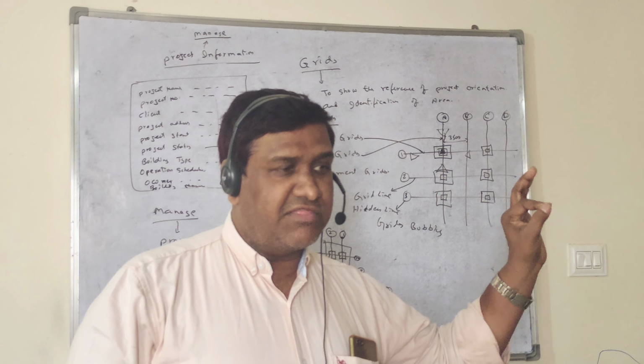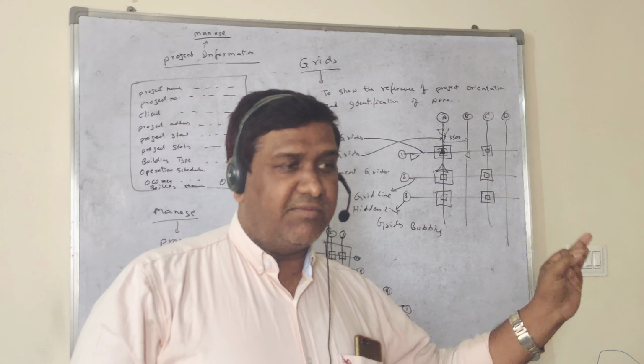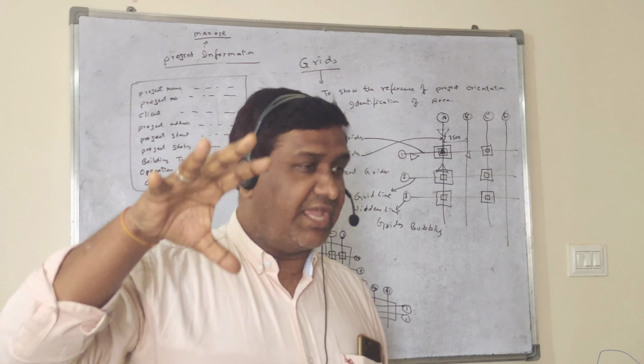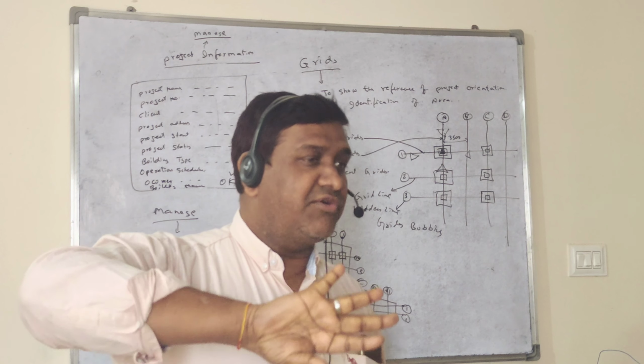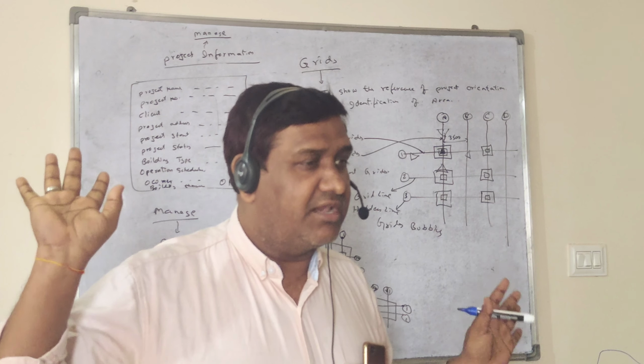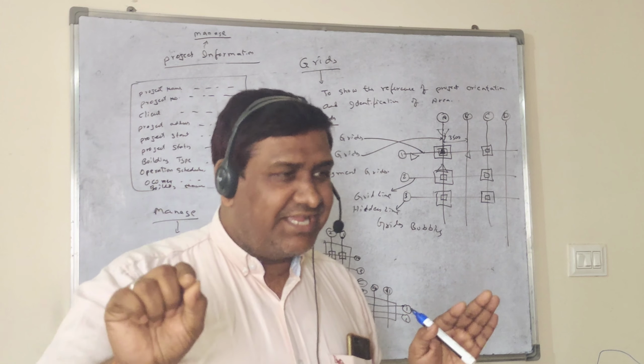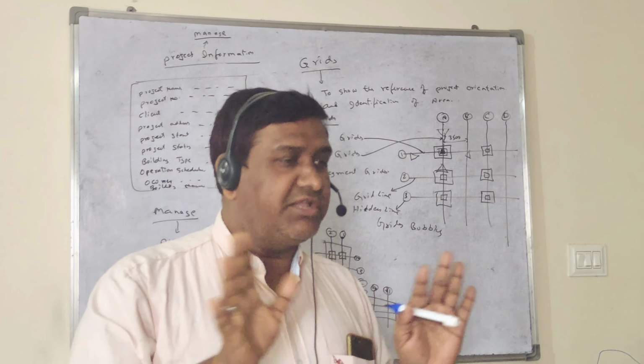If you set the units from millimeter to meter, what will happen? Automatically, whatever presentation you have ready in millimeter is going to be changed into meter. No need to delete the dimension and redo it in meter.